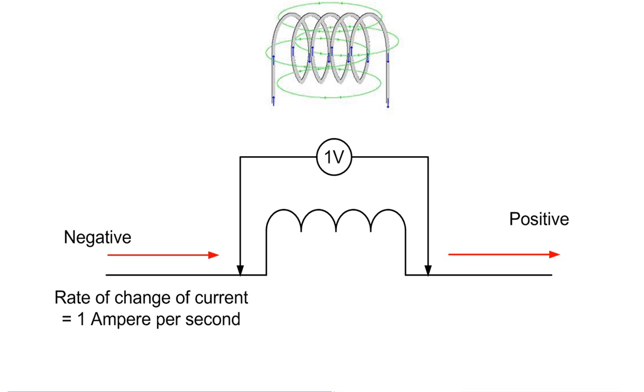What you do need to understand, but you won't be assessed on, is what inductance is. Inductance is the electrical property of an inductor which opposes changes of current through it, just like a capacitor did. A capacitor had an opposition to change. That opposition was to a change in voltage, and that opposition was equal to XC equals 1 over 2 pi FC. With an inductor, the opposition is to changes of current, not voltage. And that opposition is called inductive reactance, and XL equals 2 pi FL.